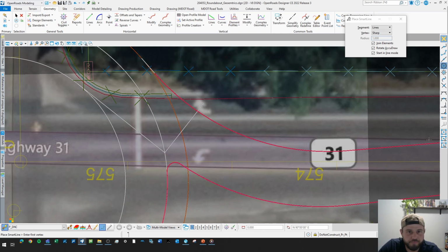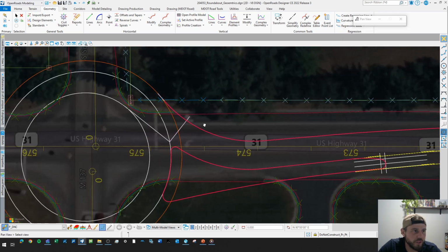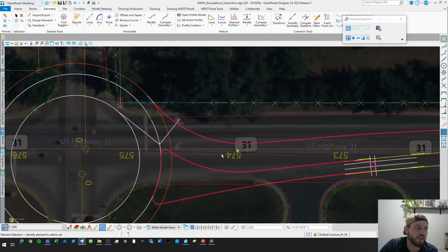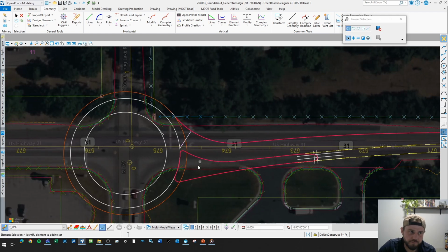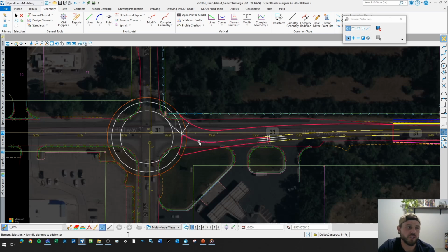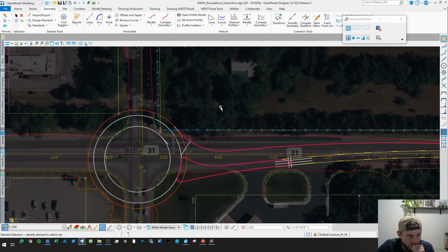From this point, you can already tell it's not wide enough, 25.22 feet. So I already know there's no way I'm fitting two design vehicles in this area. This has got to be widened out closer. This is where I can start using these to give me a little bit of an adjustment. If I bring this down, it gives me a little more deflection. That's one option. That's probably great for the design vehicle, but that will change some of your fastest path parameters. This is the freedom you get with setting it up this way. As you're doing iterations, you can tweak these things, go back through your fastest path, run your auto turn, and then see what works for you.